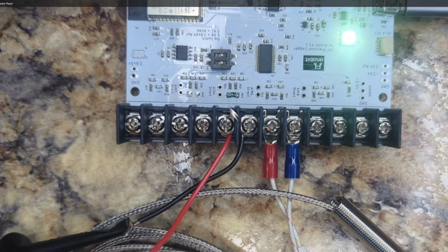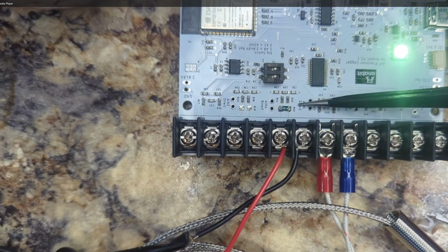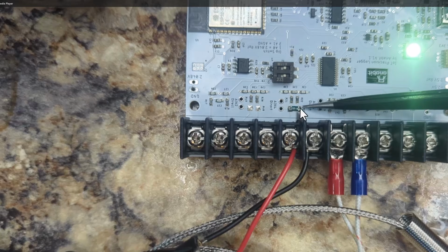Right here, I have a sense or shunt resistor that's 0.1 ohms that we're going to use for the current measurements. The idea is we put current through this precision shunt, we measure the voltage drop, and we use Ohm's law to get the current value. The AIoT precision logger board has two blank pads on two of the differential channels. These don't come populated, but they're 1206 in size, and they allow you to put a shunt resistor or even possibly a precision resistor for ratiometric measurements. So once again, very flexible measurement setups, whether you're doing straight voltage, current, or resistance.